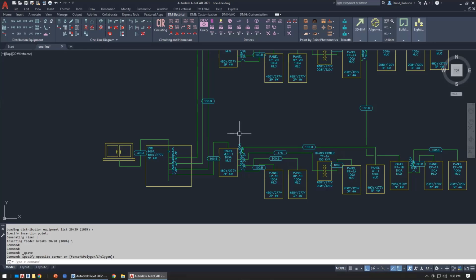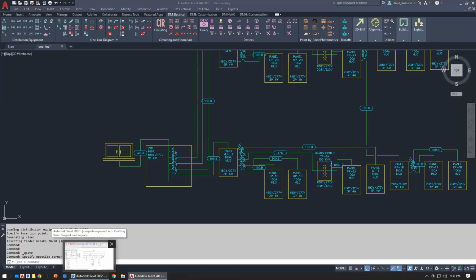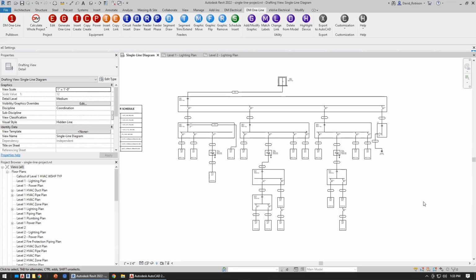You're laying out the panels using our standard functionality to generate this. You can do it because it's just a matter of how you're drafting things, if you're drafting them in a riser or a one-line configuration. So we don't have the generate riser written yet. That's going to be in a future update. So if you need a riser, draw that by hand. What we're talking about is the one-line version, which is something that looks like this. So just keep in mind that this generate command will generate just the one line.